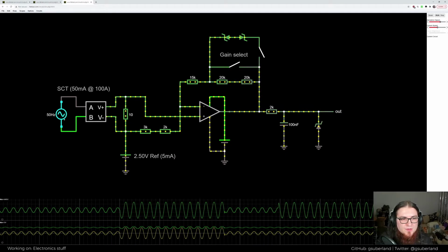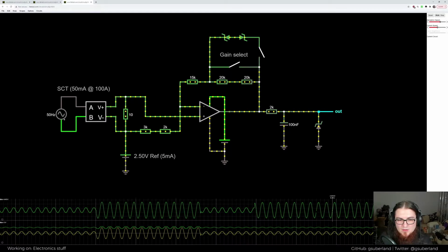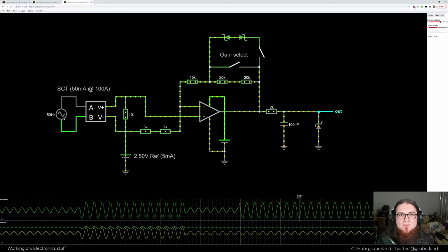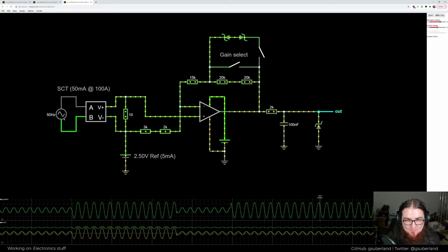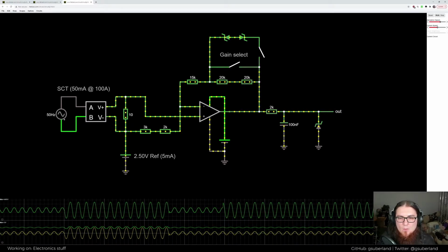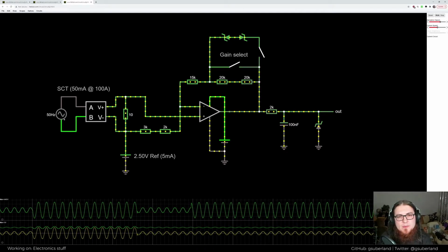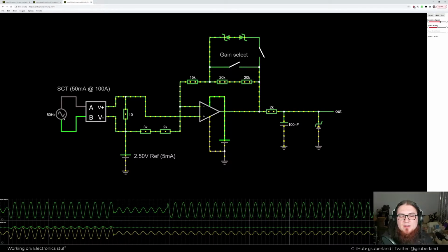So for a 32 amp input, we can now see that it's generating these same peaks again. It's back to this 4.45 volts. It's generating these high peaks and using the full ADC range, which is ideal. Now, having just a physical jumper that you have to plug in and out of the board is okay. But the software also needs to know about it. You could have the user select the right gain value so that they get the right values out of the board.